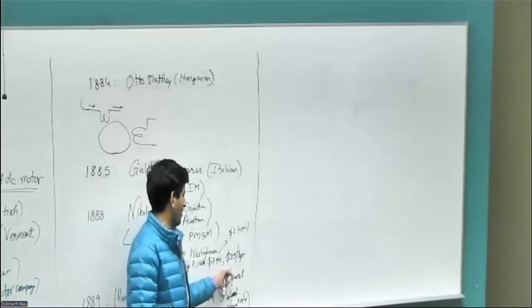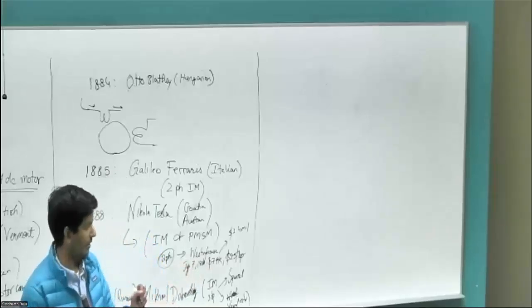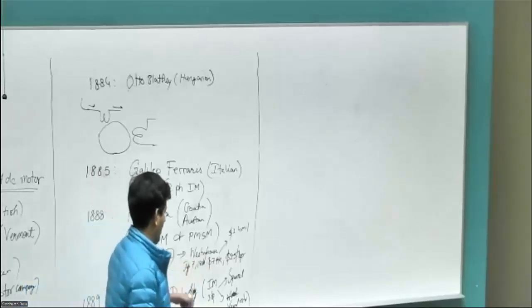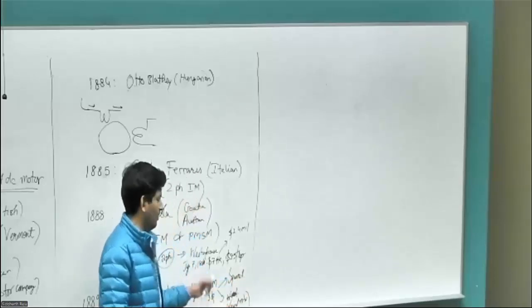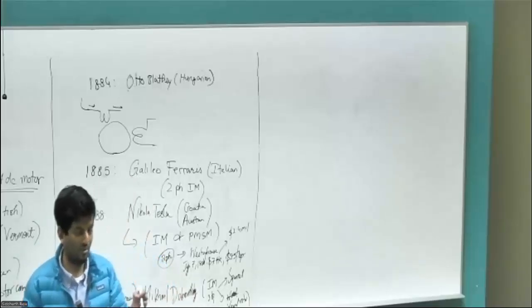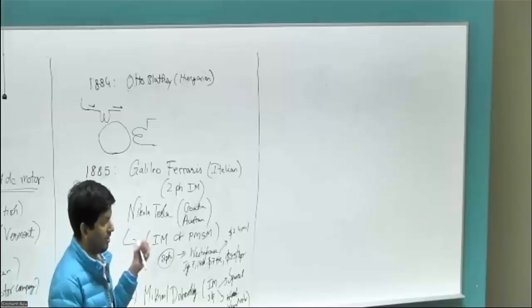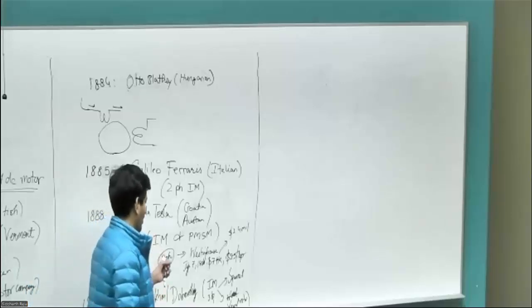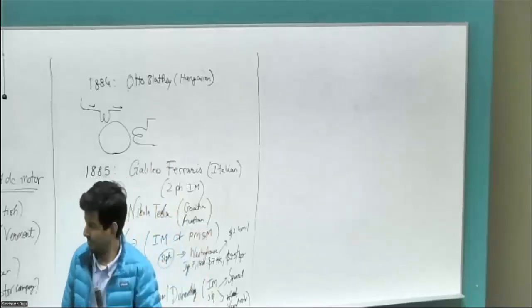It's called as such because the rotor looks like a squirrel cage. It does not have a magnet. And I don't know which monster creates cages for squirrels, but apparently that's what it looks like. And I haven't seen a squirrel cage, so don't ask me if that's true. The advantage of these induction motors is that they do not use a permanent magnet or any sort of magnet at all on the rotor structure. There is just a bunch of copper rods shorted together, and that somewhat magically interacts with the stator created flux and starts to rotate, right?